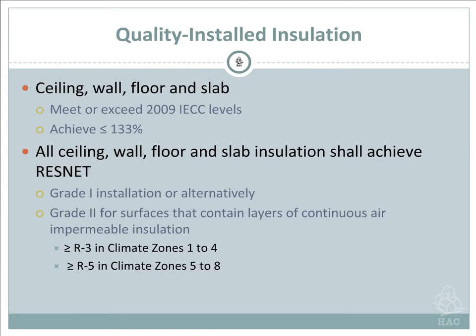All ceiling, wall, and slab insulation should be installed. Again, depending on what climate zone you're in, climate zones 1 through 4, it's equal to or greater than an R3. Again, an R5 for climate zones 5 to 8. In New Mexico, we're probably using the blue board on those, so we're going anywhere from 5 to 10 on our values on the slabs.